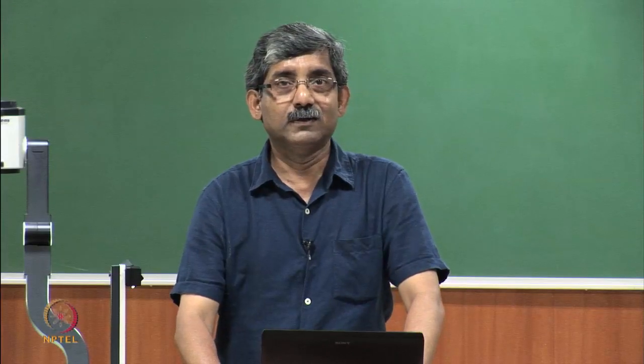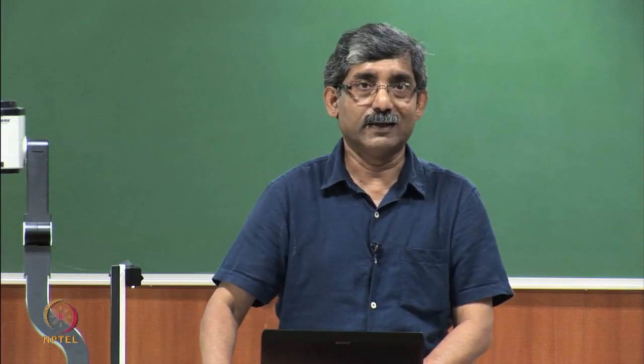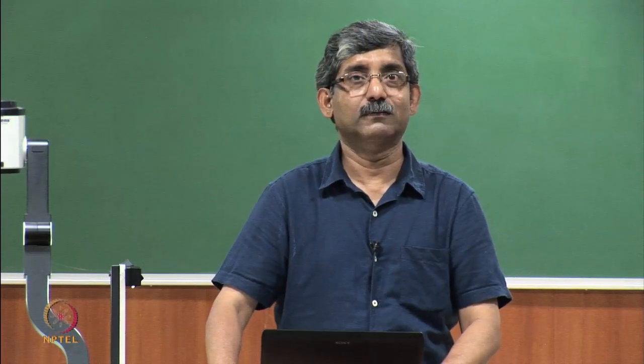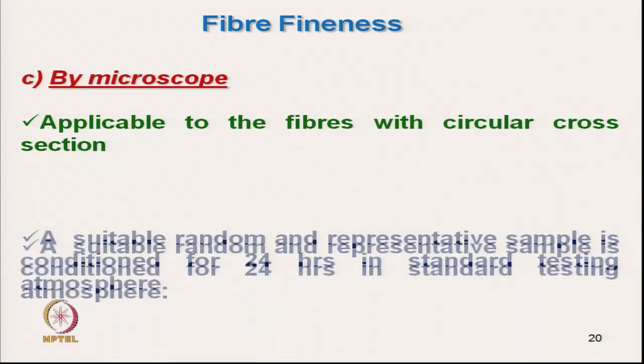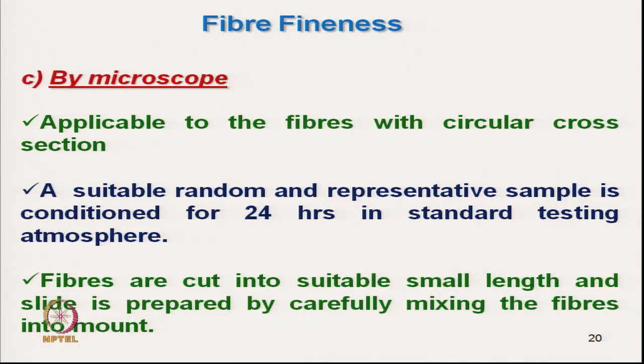Hello everyone. So, what we are discussing is the measurement of fiber fineness. In the last class we discussed fiber fineness, fiber diameter measurement by the microscopic method. We mentioned that it is applicable only for circular fibers, where the cross section is circular in nature, and after proper conditioning we have to put the fiber, we have to mix the fiber